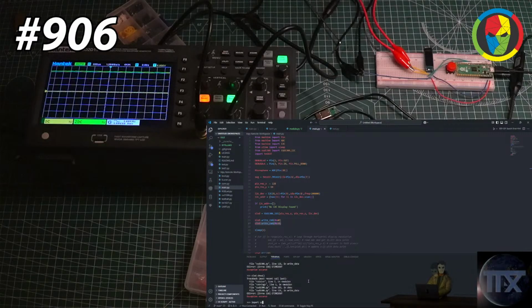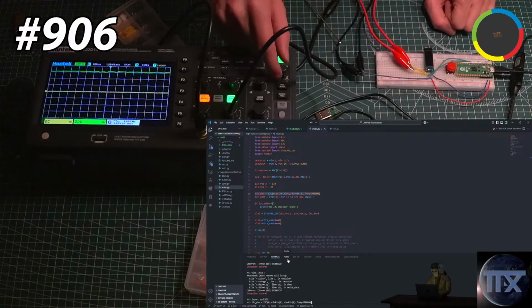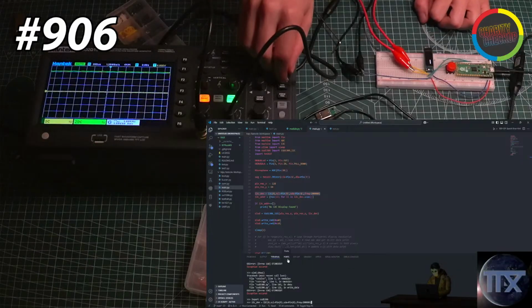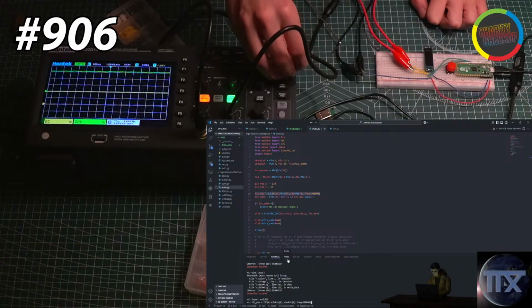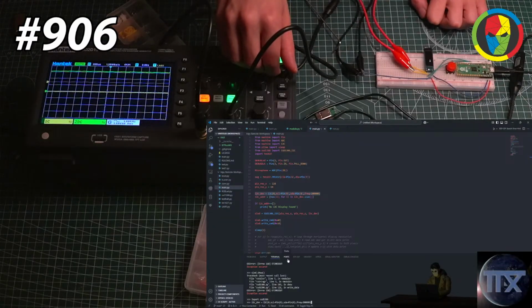Another thing that's pretty important on the oscilloscope is the trigger. It's the knob right by the green glowing button in this corner, the trigger level. When you move that, you should see a dotted line move. Oh, I see it. Yep. And if you put it between 0 and 3 volts, what the trigger does is it says, hey, if a signal comes in and crosses this threshold, then pause. Oh, makes sense. Okay.